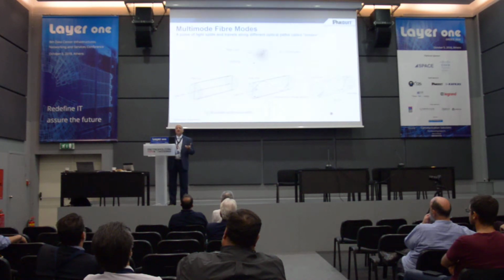The fiber is a waveguide, and you have light that's propagating, which is a wave. So the light can only propagate in certain ways, so it interferes with itself constructively. And it turns out that in multi-mode fiber, there are only 380 different modes or paths that the light can take so that it constructively interferes with itself as it propagates through the fiber.